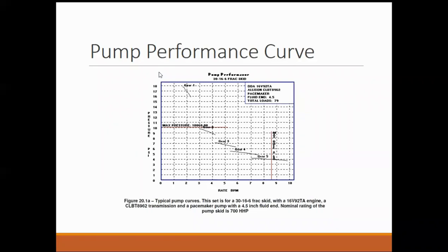In the same way, the pump pressure is governed by the RPM at which the pump's engine is rotating, right? So at what rate do you want to pump the fluid into the well, and at what pressure? These curves will help you to select the correct pump, that, okay, this is the pump I require for pumping this job. Not all jobs may require the same kind of pumping system. They might require a different kind of pump with a different hydraulic horsepower rating and different type curves. So you have to understand this.